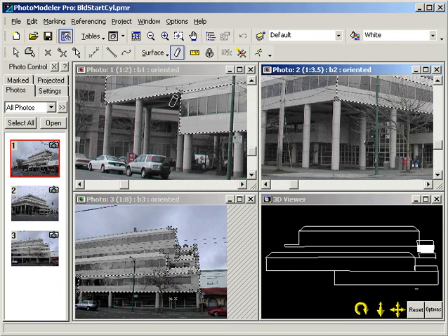We will use photos 1 and 2, which capture the area in question and have good angle rotation around the poles. On photo 1, mark a point at the top part of the cylinder along the left edge. Then move the cursor and mark a point towards the bottom along the same edge. We mark the point at the bottom as far as we can see. This finishes the one edge of the cylinder. We then move over to the right edge and mark 2 more points. When finished, the cylinder mark appears with 2 edges and a joining line in the middle.